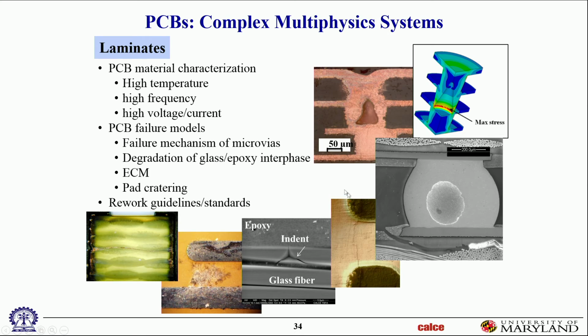Okay, we also get other kinds of mechanical failures. This is fatigue failure in vias because of out-of-plane expansion. This is the cross-section of a printed circuit card, so the vertical direction is the thickness direction. The circuit card expands too much in the thickness direction. Each time you heat it up, it expands, and then it shrinks down again, and that makes a cyclic loading in the copper. Eventually you get fatigue failures in the barrel, and that causes an electrical open.